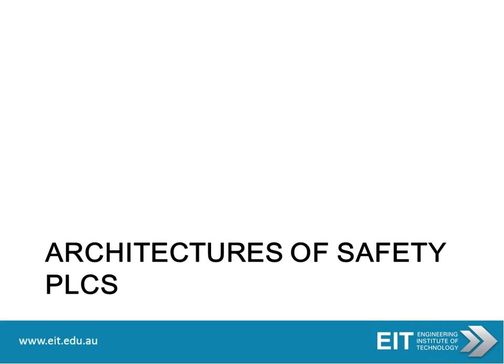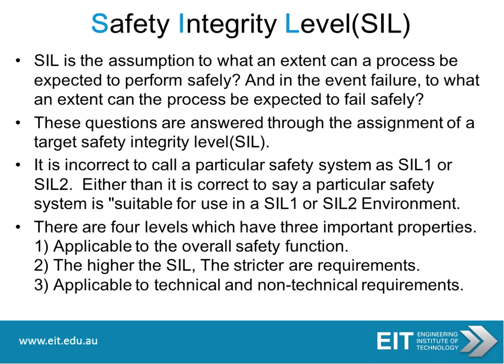Okay, moving over to the architectures of safety PLCs. Now, let's first look at safety integrity level, SIL. This is the assumption of to what extent a process can be expected to perform safely, and in the event of failure, to what extent the process can be expected to fail safely. So it's perform safely as well as fail safely, and these questions are answered through the assignment of a target safety integrity level, SIL.